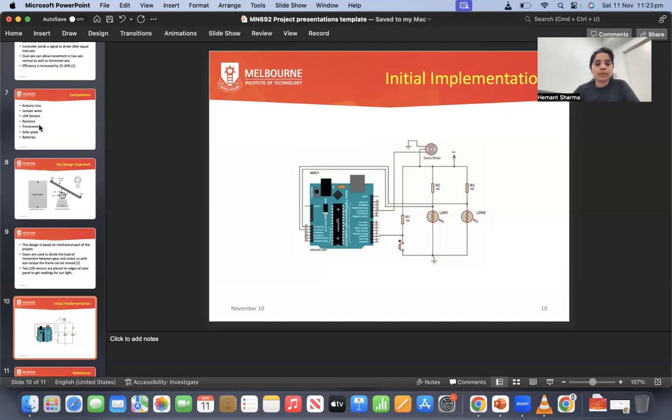For programming the Arduino board, we need to connect it to the laptop computer using a USB cable, attaching the PC and the controller. Arduino will be powered by the USB connection, but an external battery can also be used if needed, which keeps Arduino active even if it's not attached to the PC. For basic understanding, we will start with a basic program, blinking the light on the Arduino board. First, we will download the Arduino IDE for basic coding on Arduino.